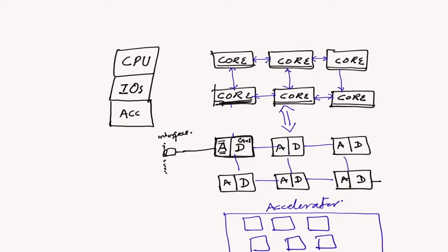Okay, so then this whole network also needs to talk to this in case they need to send information to an IO, or they need to talk to CPUs, so that they're able to send that over. So the whole thing is talking to each other. This network between different processing elements is also called a network on chip. So in a system on chip, we have all these individual components, and the person or the group who creates that system on chip also needs to connect all these things together.